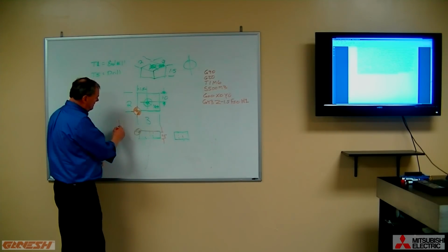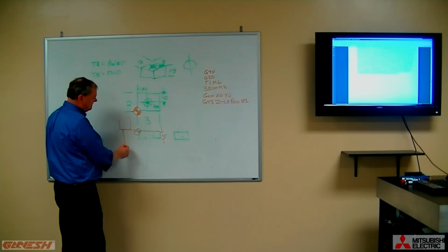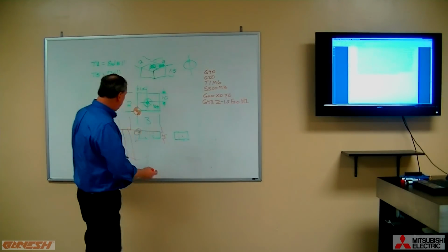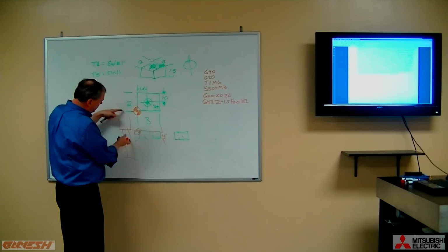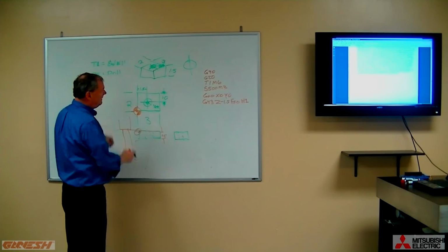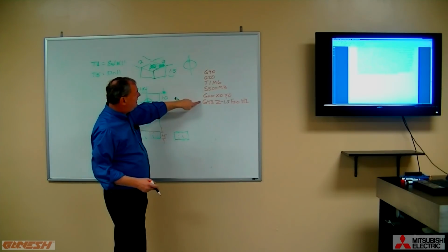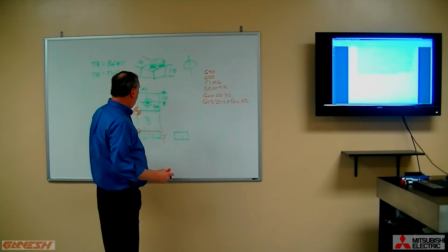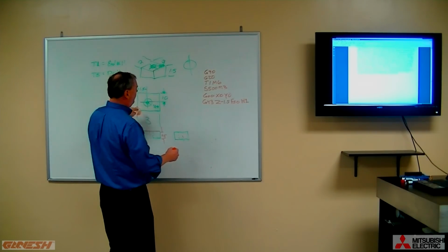Because if we didn't call up a tool length, we would slam the spindle face and our tool would be somehow crashed through the part. So what H1 does is it says, okay, I've got this long of a tool, so I need you to stay up this much higher. So this kicks in our tool offset for tool number 1. And then we're going to just mill around this part, let's say.